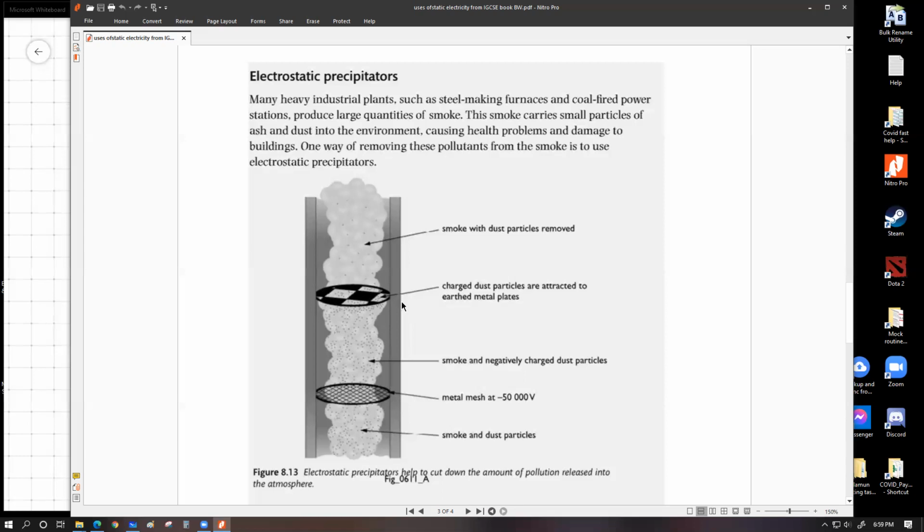One more additional thing that you need to understand is that over the duration of use, let's say you install this on a certain month's first day and then keep on using it, as time goes by, these metal plates will slowly accumulate a thicker and thicker layer of dust particles, and that thickness of dust is going to work as a sort of barrier that will reduce the induction process. So every once in a while these things need to be cleaned.